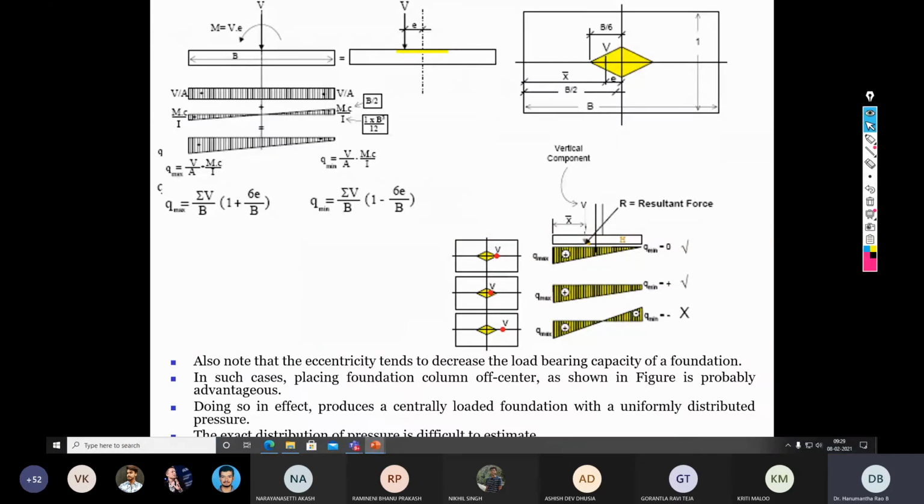Okay. So this is the pictorial depiction of the same footing with eccentricity, in terms of the middle third rule. You can see the development of Q max and Q minimum when it is just on the border of the middle third. So this is one middle third, this is another B by 3, and this is another B by 3. When the location of the footing is on the verge of the middle third, then the Q minimum becomes 0.